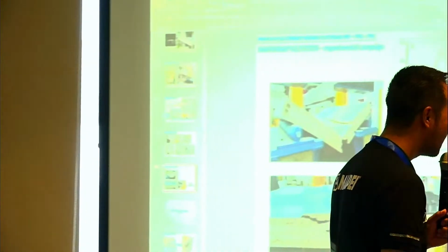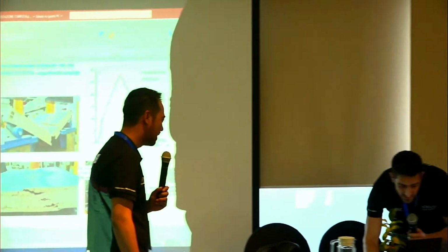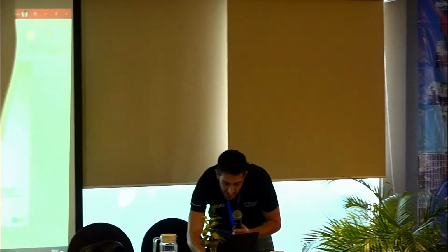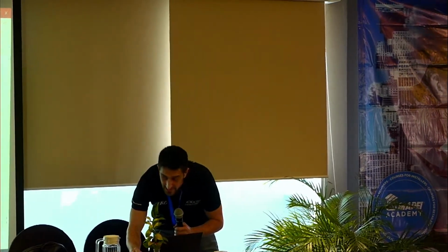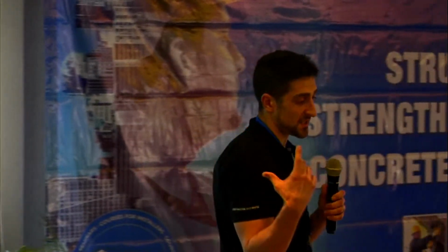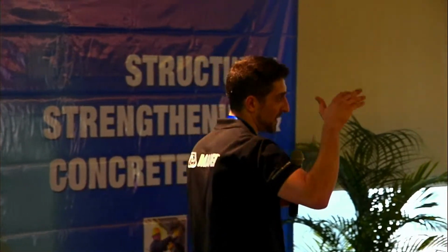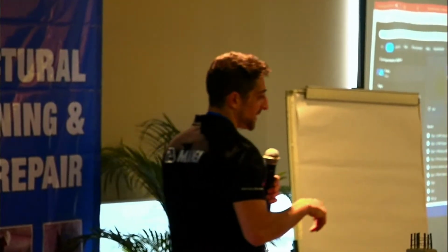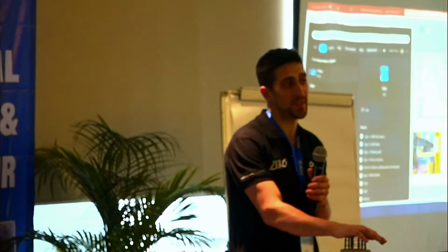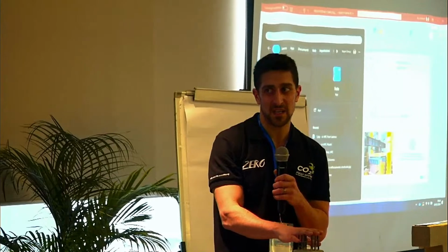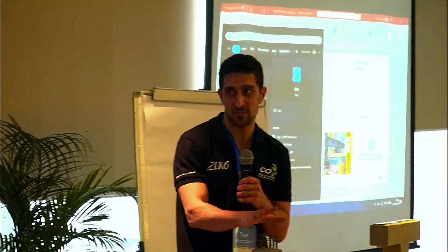This can also be applied on ceilings. Do you have some picture of the ceiling? Yes, it can also be applied in the ceiling area. But I don't think that you will have this kind of application, because basically we apply this system to prevent the falling of the hollow core slabs we have in Europe, and I think that in Indonesia you only have concrete slabs. That's why it is better not to use it.